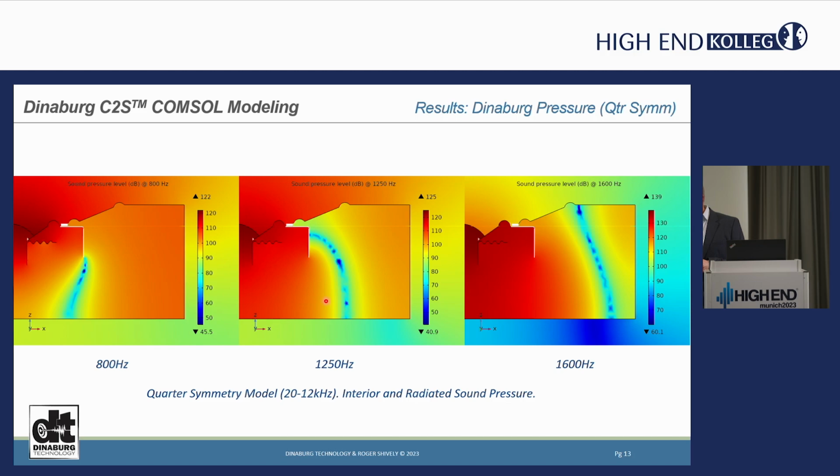Yes, but not too much, because there was a point where, part of the simulation was how small of a box can you use. So we had started with a much larger box and a much larger design, so we optimized it down to a 3-inch. The first one was a 6-inch active speaker with a 12-inch passive, and a larger box of about 20 liters.